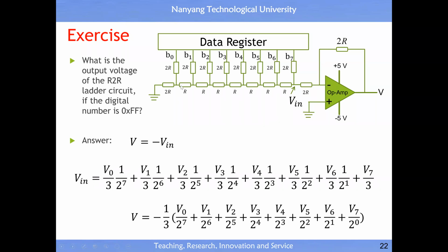Now you look at this voltage. What will be the voltage? If let's say you have a voltage here, then what will be the voltage here? Because all the rest of the network of resistors is equal to R, that means it is a half. So then it is this one divided by 2. Once you have a voltage here, this voltage first divided by 2, you will get the voltage here. Another divide by 2, you get the voltage here. By another 2, you get the voltage here. All the way you reach the voltage here.